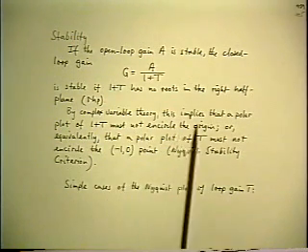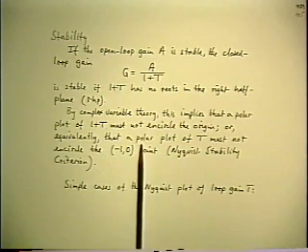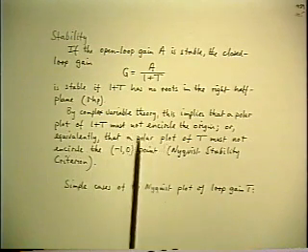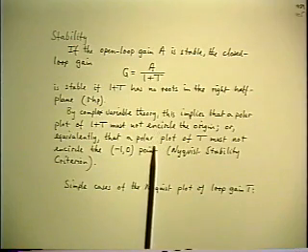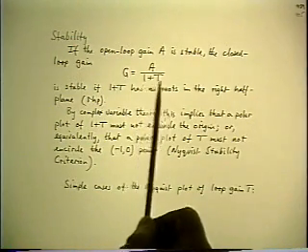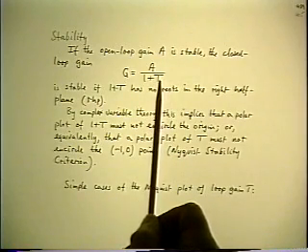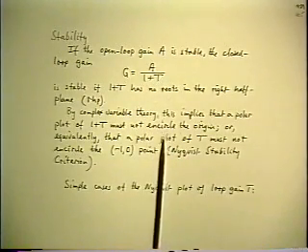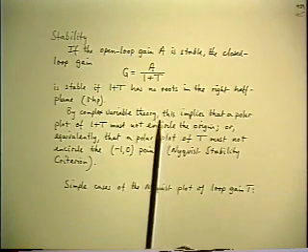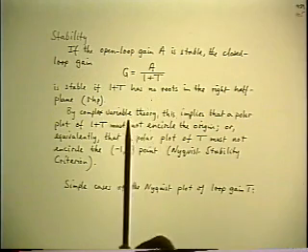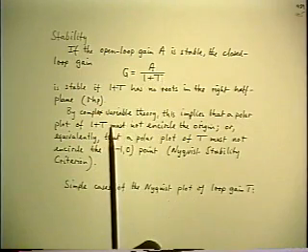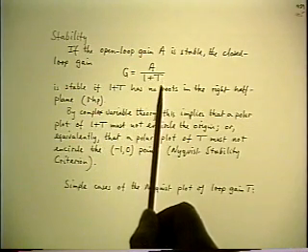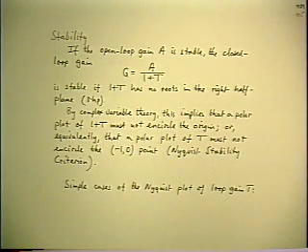Now, it takes some complex variable theory to derive that relationship, and this is the standard bookwork that you find in the books to do with Nyquist stability criteria. So I won't go through that derivation. Usually there's one further step. Because F is actually a derived quantity, T is really the fundamental quantity, usually that result is also translated to say if the contour of F does not encircle the origin, since F is simply 1 plus T, there's a unit shift. And the equivalent condition is that the polar plot of T should not encircle the -1 point.